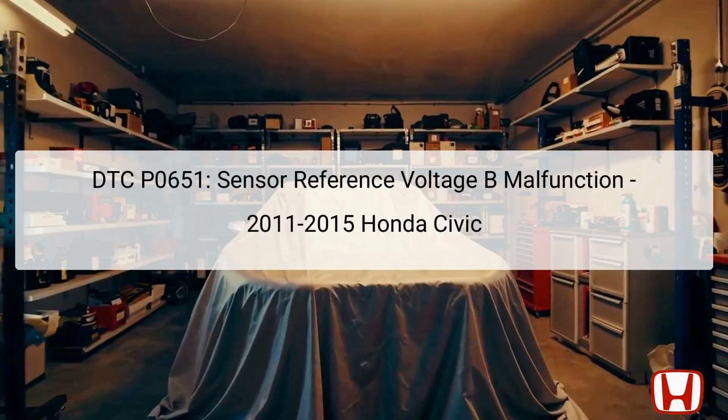The DTC P0651, which indicates a malfunction related to sensor reference voltage B, is a diagnostic trouble code that affects certain Honda Civic models from 2011 to 2015. This error code typically implicates the vehicle's engine control module, ECM, as the central unit responsible for managing the car's electronic sensors and circuits. When this code is triggered, it suggests that there might be an issue with the voltage provided to specific sensors that rely on the reference voltage, which are essential for the vehicle's performance and operation.